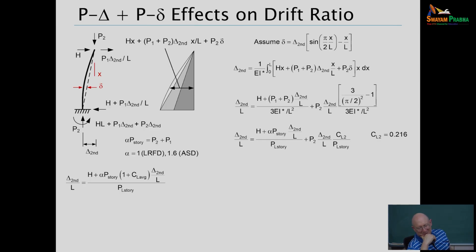So now that we've defined a term C sub L, when Bill LeMessurier published his seminal paper that introduced a lot of this in the AISC Engineering Journal in 1977, I typically don't use that and don't provide that because it's all in allowable stress design, so you've got a lot of ugliness to work through with all the allowable stress stuff. But he had charts where you could go in and calculate a C sub L for every column in the frame. Now that's a lot of work.